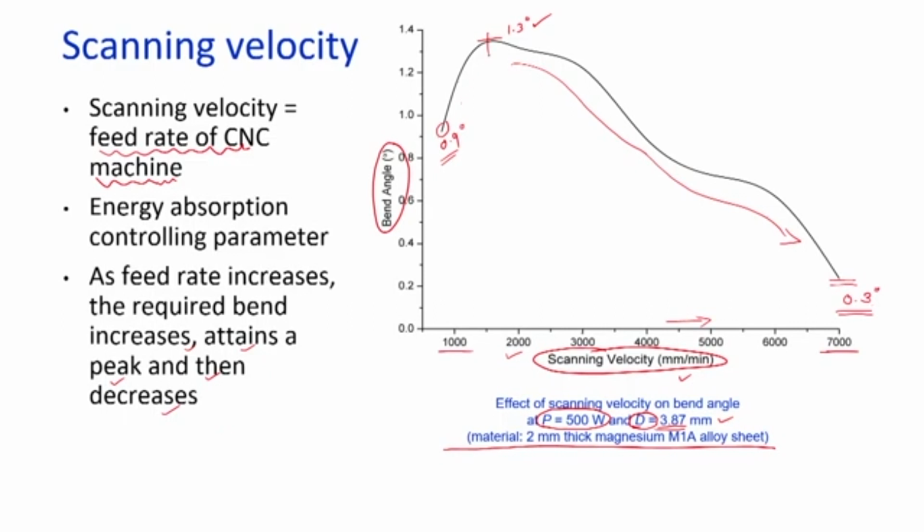With increase in the scan speed, initially we could get good TGM, that is, a steep temperature gradient was achieved. But to get more bend angle we increased the scan velocity, and as we increased it there was not sufficient interaction time of the laser beam with the work part. Due to this less interaction time there was no proper dissipation of heat, which is at least required for the plastic deformation. So, too much faster speed is not required in a successful laser based bending operation.